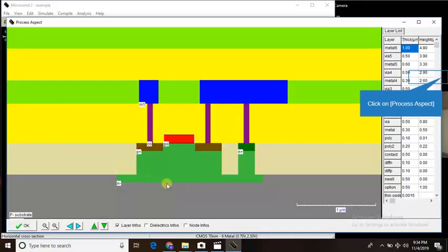Okay, so this is a PMOS transistor which is sitting in the N well. The green one is the N well. This side is the drain of the PMOS. This is the gate; the red one is polysilicon material. The drain is connected to metal one through a contact hole, and the source is connected to VDD through a contact hole here, a metal layer. And as I said, we have opened an N plus contact to take a contact from the N well.